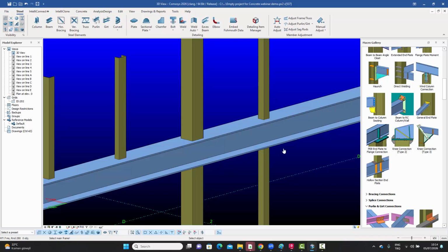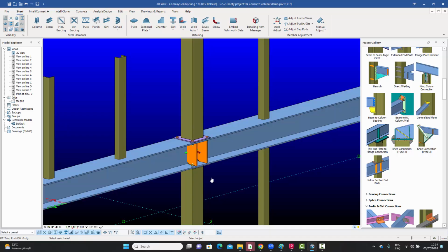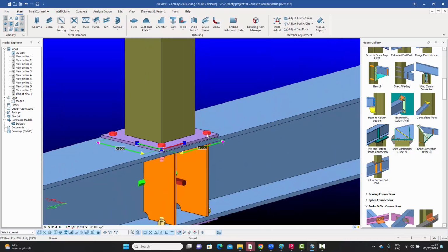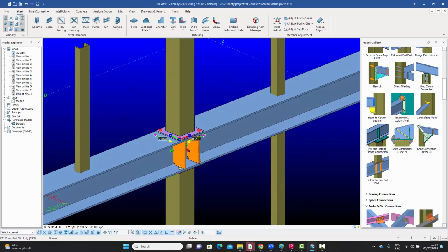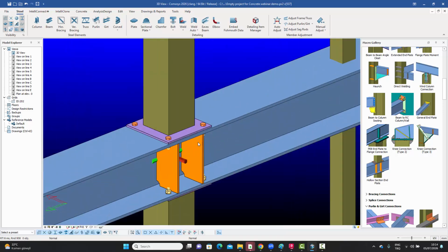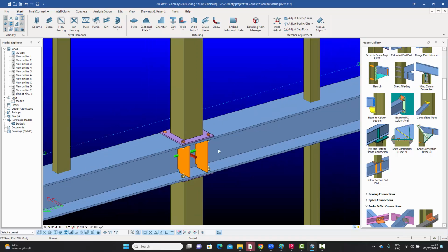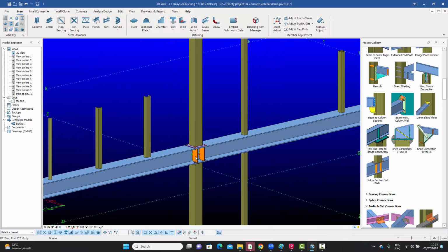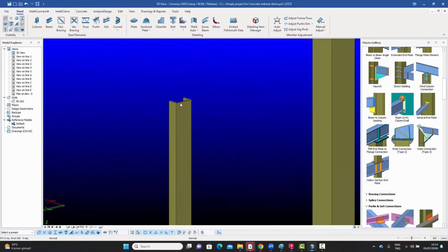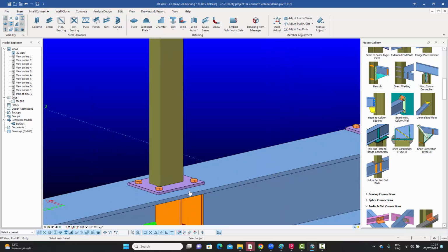And if I were to click on this and select the main beam first, and then select either one, in whatever order, you will see that it creates an end plate connection, double-sided, with the stiffeners in between. So very conveniently, with just a few clicks, you can create this connection. You could have done this using other options in a couple of steps before, but now you can do it directly. Now, this doesn't necessarily only work with hollow sections. If you had a channel sitting on it and it was one-sided, you could still go like that, and the channel would be connected.